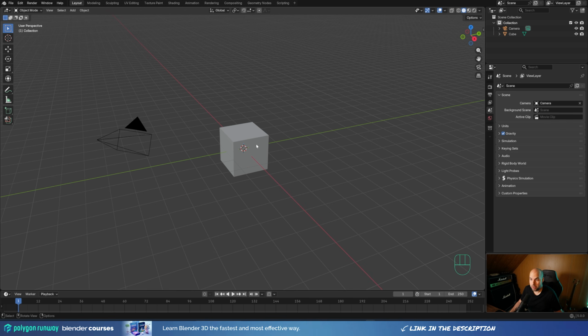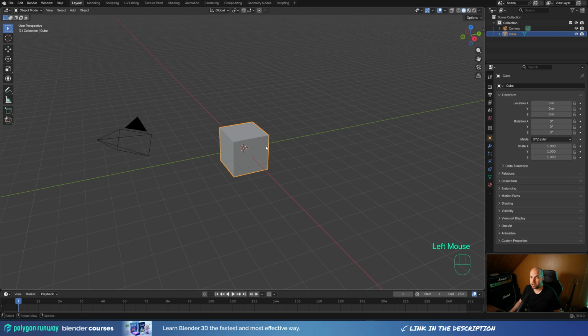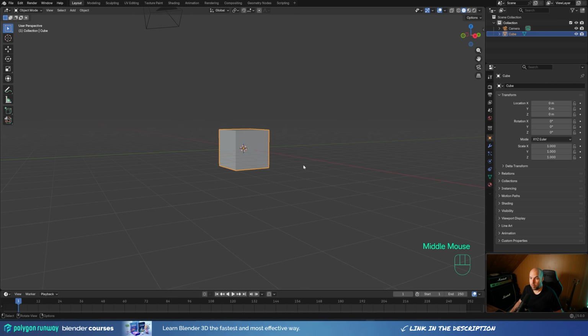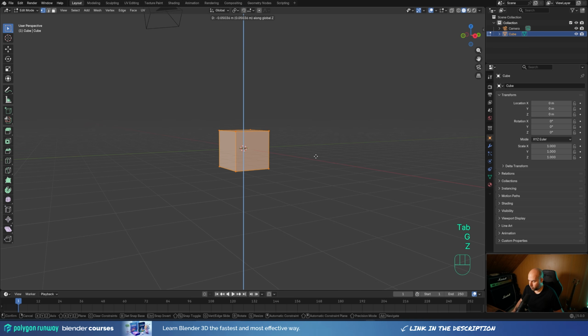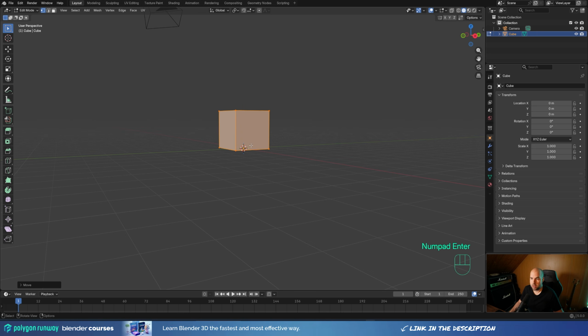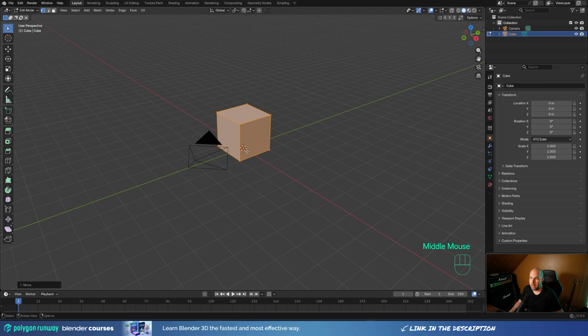And we can actually use the cube, so this is again one of the videos where it gets to shine, so let's just select it. But I want the origin point at the bottom there. So what we can do is to just push it up in the edit mode. Let's tap into the edit mode, press G then Z, and we can enter 1 and just hit enter to move this 1 meter up, because we know the default cube is 2 meters high, so if the origin point was in the middle, we only need to move it 1 meter up, and now the origin point is at the bottom.